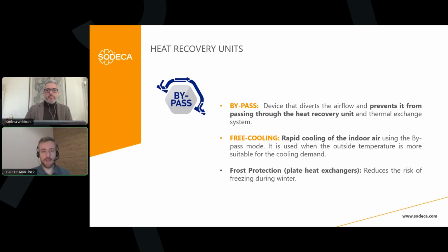Okay, the bypass is a device that diverts the airflow and prevents it from passing through the heat recovery unit. So we are preventing the thermal exchange from occurring. Why? Because there could be situations where it is necessary to supply direct air from outside. For example, if we need a free cooling. What is a free cooling? A free cooling is a rapid cooling of the indoor air using the bypass mode.